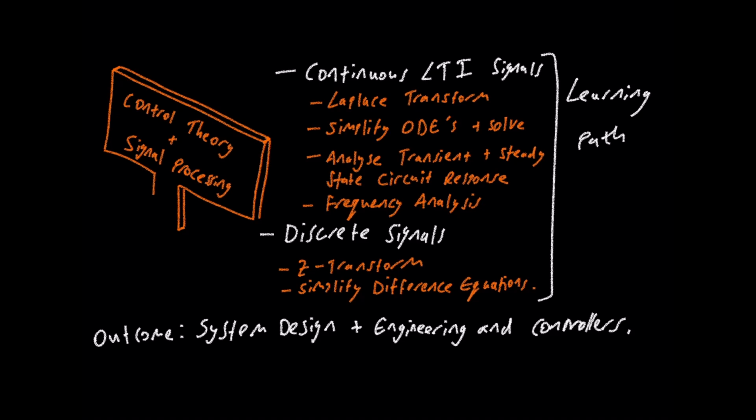The aim is to obtain a transfer function, a simple algebraic expression in Laplace space which encodes all of the physics of a circuit. You can analyze the transient and steady-state responses involved with things like charging up a capacitor and more. Frequency analysis is another result from this, where you can see how the gain of certain frequencies might be amplified or attenuated more than other frequencies.